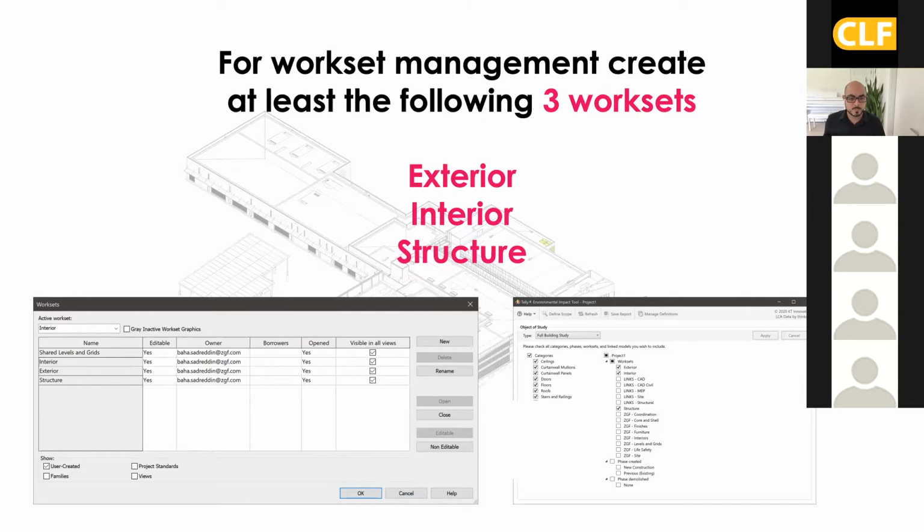But as you see on the bottom right of the screen, in Tally, you could filter a whole building LCA by categories of families, ceilings, and everything else, but also by work sets. When you filter by categories, let's say a ceiling that is on your structural model by accident, you can't really filter it. But by filtering through work set, you could really choose what to include and what not to include. So I highly recommend using work sets.